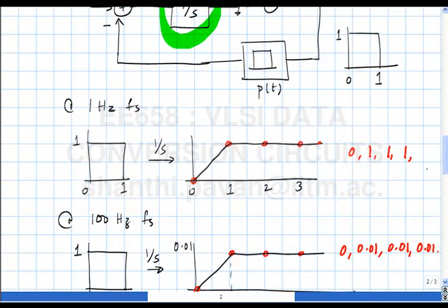Another practical problem which I have highlighted in many of my classes before, and people still continue to make mistakes, is that when you are implementing things in MATLAB, it does not make sense to work with absolute frequencies. If I gave you an assignment saying do something with sampling at 1 gigahertz, it does not make sense to take 1E9 as the sampling rate, because if you had a 4th order filter, then you will have something of the form s by omega naught, whole to the power n.